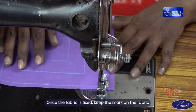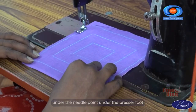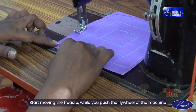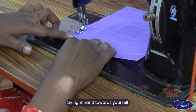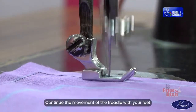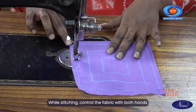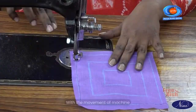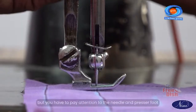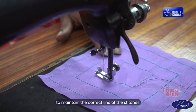Once the fabric is fixed, keep the mark on the fabric under the needle point, under the presser foot. Start moving the treadle while you push the flywheel of the machine by right hand towards yourself. Continue the movement of the treadle with your feet. While stitching, control the fabric with both hands. With the movement of machine, the feed dog will automatically transport the fabric, but you have to pay attention to the needle and presser foot to maintain the correct line of the stitches.